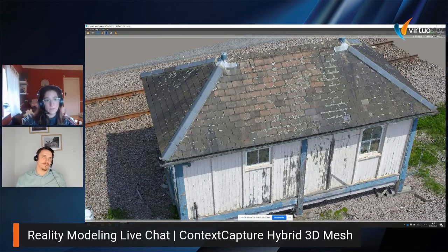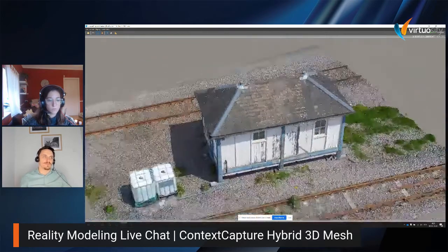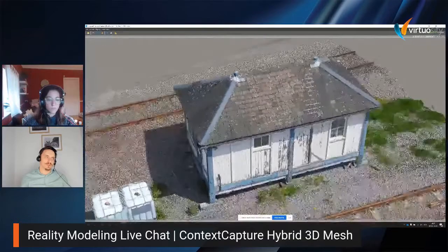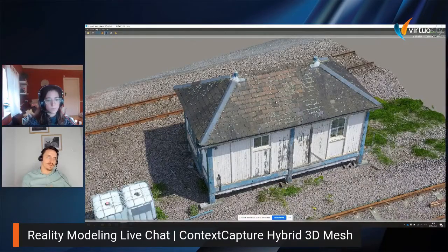Let's say that in the market now, each bigger and more serious surveying company has a laser scanner, or a smaller one, like the BLK360 from Leica, or they go bigger, for example the RTC360 or a Faro Focus. So they already have a system to do it, and those are pretty robust. They can produce a point cloud, but creating a mesh from a point cloud is still a little bit tricky, because many software packages will miss information about normals for the points, or they will be rather expensive solutions.